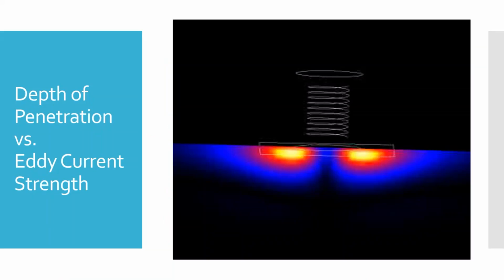If we look at a heat map of it, this is where you can see the eddy current coil up at the top with what they call a wear face, the thing that it slides along the surface. And then in this case, the part, it's showing the strength of those magnetic fields, okay? That's going on down inside. So it looks something like this.